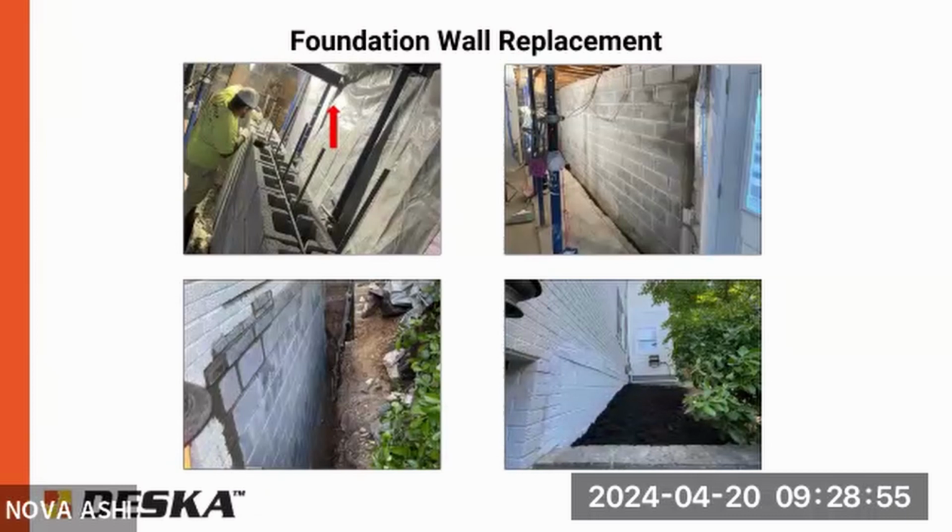So generally, if you're replacing something with new, it needs to be brought up to the newer code. If it's a repair, then that can be a little bit different. But ideally, the building code is the minimum. So ideally, even if it wasn't required, we'd want to bring it up to, at a minimum, the building code. But if it's a replacement, pretty much every building official requires it to be brought up to the new code.